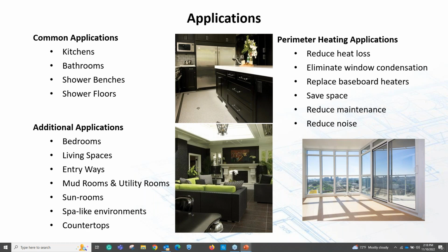If you see the nice kitchen there, what you've got to look at is that those are some smaller mosaic floors. So a few manufacturers allow you to pour a floor level over the top of their membranes, which will allow you to put those smaller mosaics over the top of it, or use LVP or LVT over the top of those.